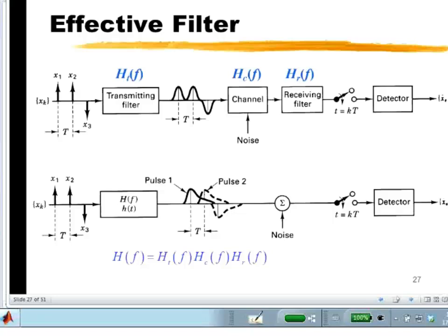And this is one of the most critical points where people can make a mistake when simulating a system, and that is how to add the noise. If I were simulating the system on the top row, I would use the AWGN command, for instance, in MATLAB, and add a wideband noise. I add wideband noise because that's what the noise in the channel would be well modeled as, but knowing always that the receiving filter is going to filter this noise.